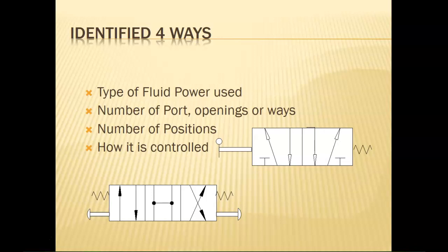This is a remote valve. Generally what you're using this for is whenever the piston hits it, it depresses, and when the piston's off it, it releases. Does that make sense? This is just a little 2 position. Another little 2 position, this one's just a push button. This one is pneumatically controlled. This one still only has 2 positions because with pneumatics, we don't always have to have a 3rd position. Hydraulics will generally have 2 to 3 positions. Pneumatics can sometimes just stick to 2.